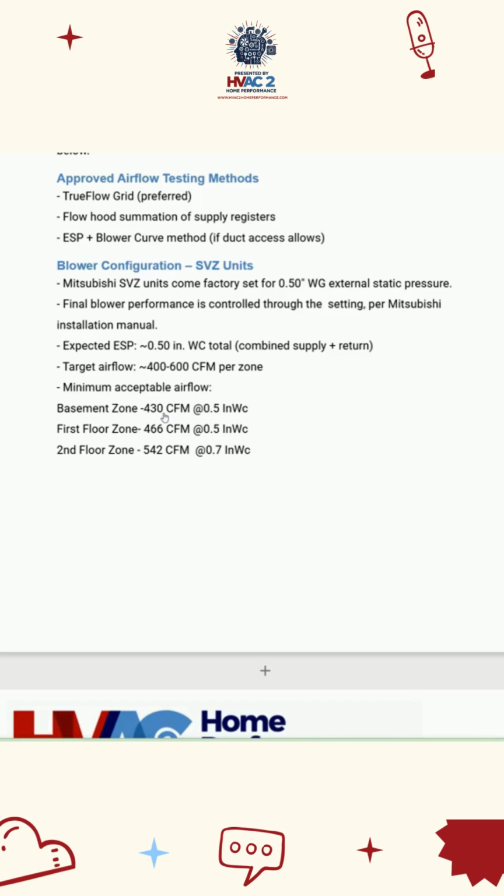600 CFM and full capacity. Oftentimes they will do that. Even for a brief moment, they'll ramp up to 600 CFM and make sure that they satisfy the load, then they modulate back down to where they need to be and keep the load satisfied. That's how these things work. So you have to be able to handle that airflow. That's not necessarily your design airflow, but you have to be able to handle that airflow in the duct system.